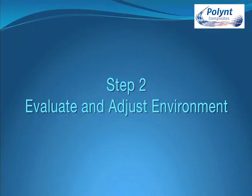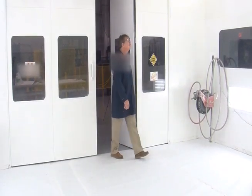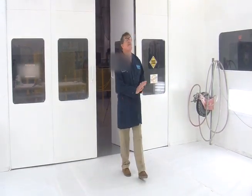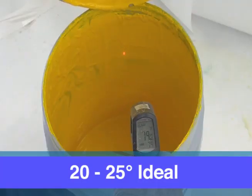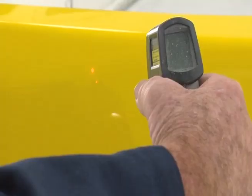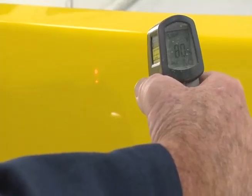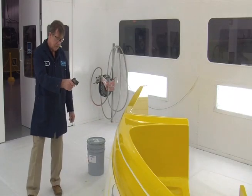Step 2. Evaluate the environment and adjust as needed. The area should be well lit, but not in direct sunlight, which would elevate temperatures. The ideal temperature of the work area and part to be repaired and material is 20 to 25 degrees Celsius. Temperatures below 20 degrees Celsius increase the cure time of the gel coat and can result in undercure and quality issues.